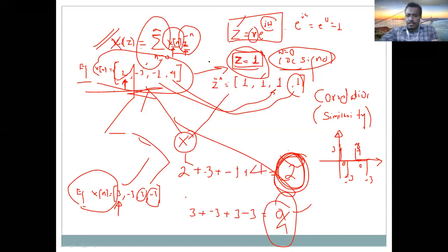If you take a pure sinusoidal sine wave, do Z transform with your signal and check the relationship. What type of sinusoidal signals exist in your signal? Amplitude, what's the frequency of that sinusoidal? Is it decreasing oscillation? Is it there in your signal? Increasing oscillation, is it there in your signal? What type of components your signal has can be determined from the transform. So that's why you can consider it as a very important concept in DSP.